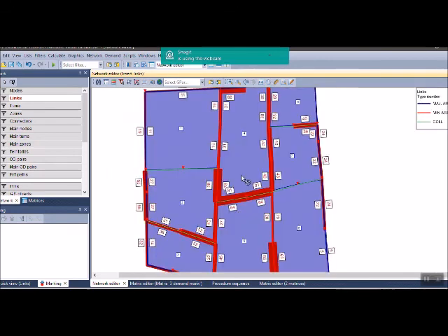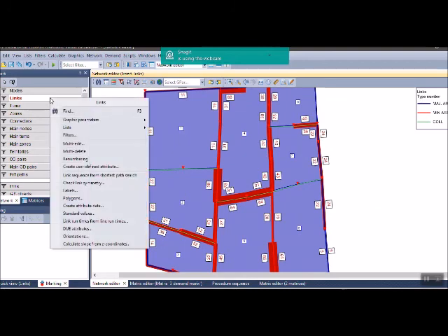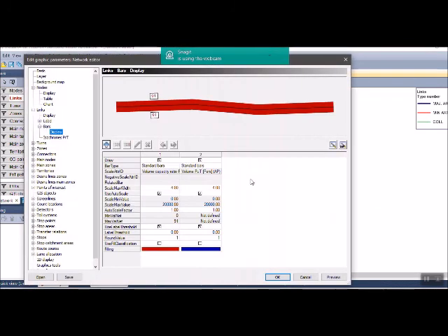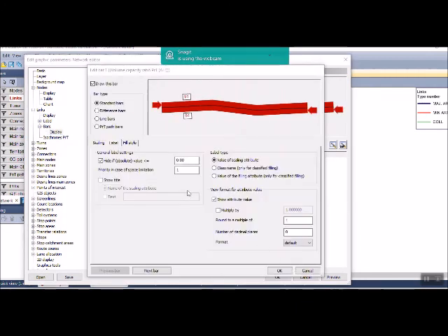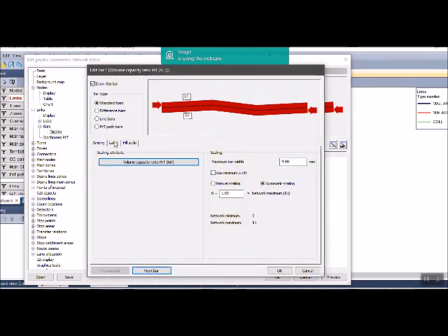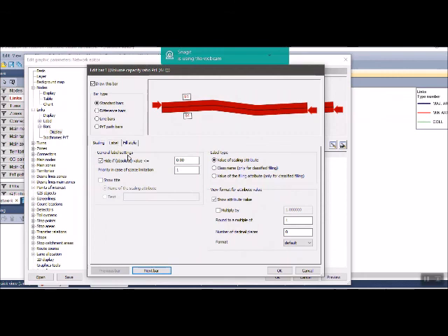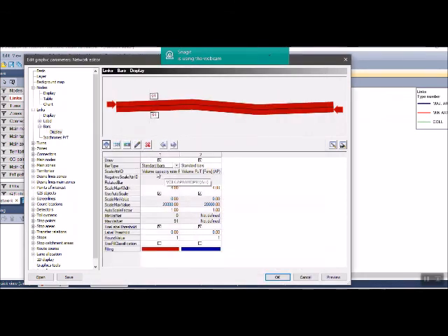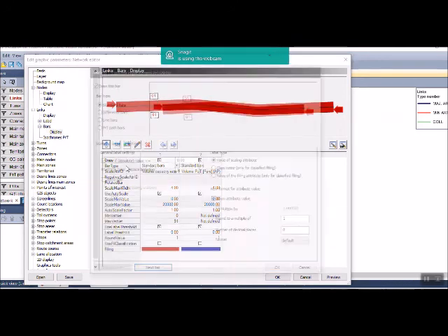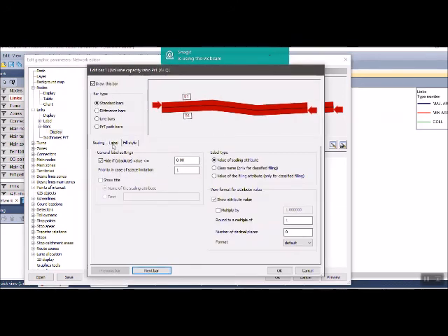For sure, you can display it as a decimal, not as a percentage. You can go in here, and in labels, oh, sorry, we just click this, double click on this bar type and go to label, and from this label you can multiply by 0.01.